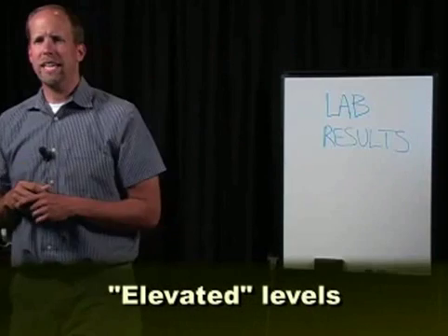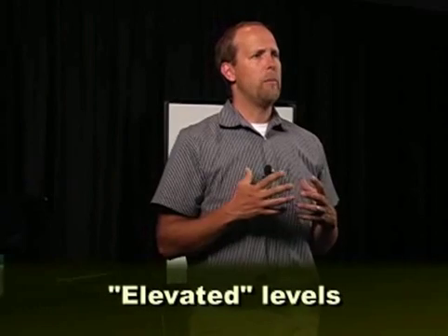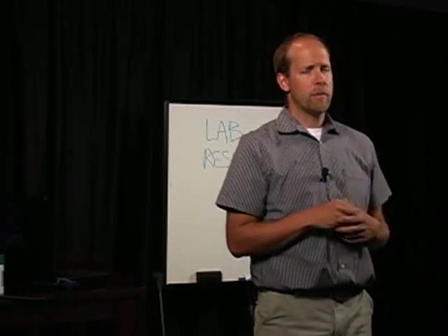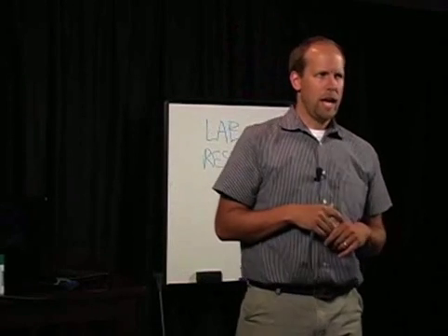Elevated indoor levels. When an air pump sample of a building interior contains more mold spores than an outdoor air sample, then the report should indicate that elevated conditions exist at the building and that the levels may necessitate further investigation.